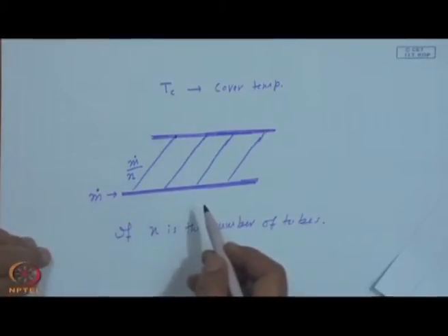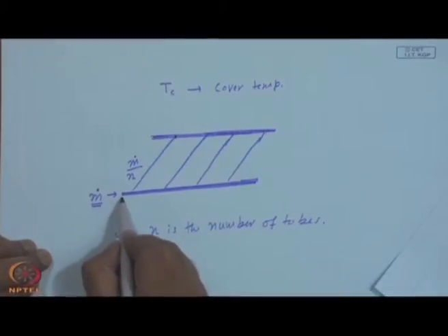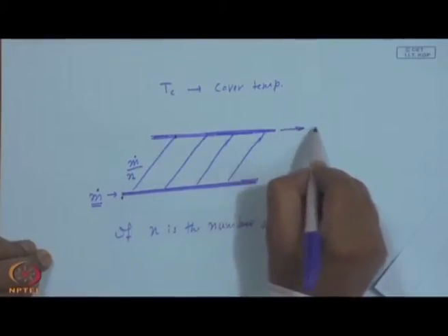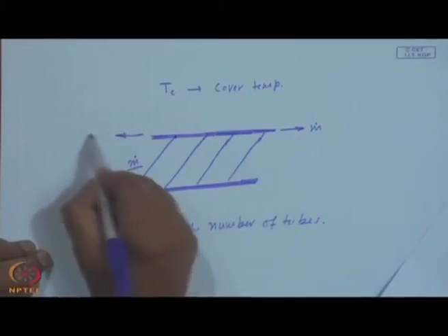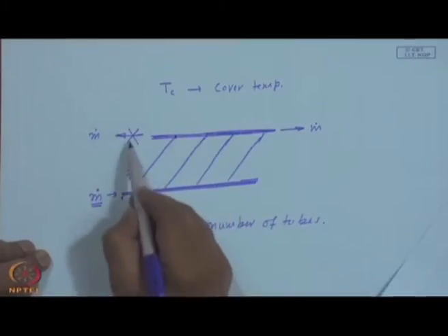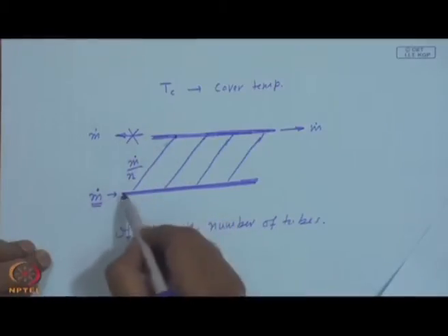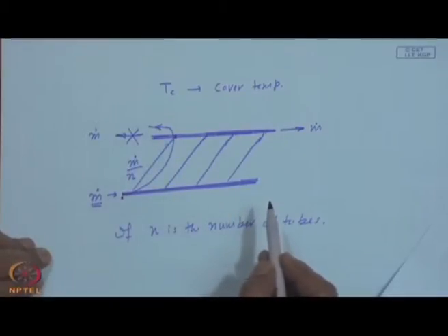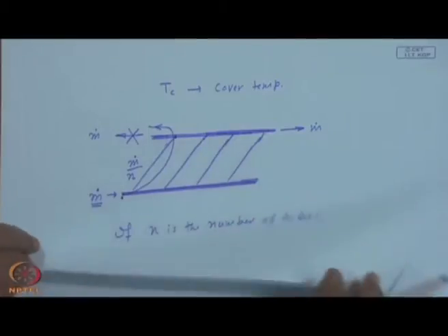So, they provide a uniform flow, or alternately if you take m dot to be inputted over here, this will be coming out as m dot and not this. If you choose the second alternative, where it enters on the same side and leaves the same side, then there is likely to be a short circuit and most of the flow will be going through the first few pipes rather than uniformly up to the last one.